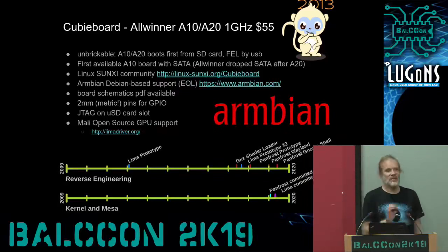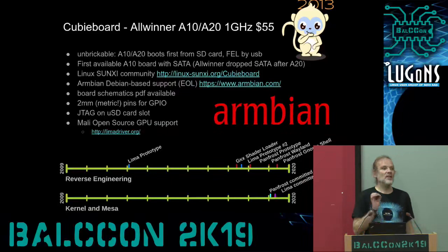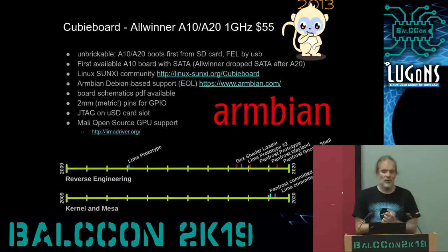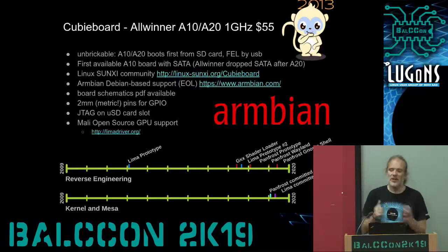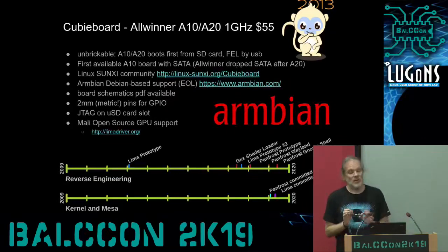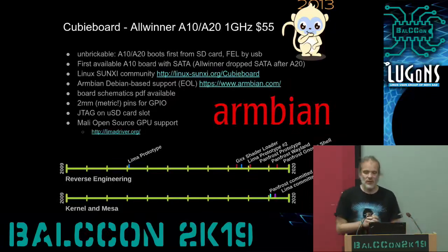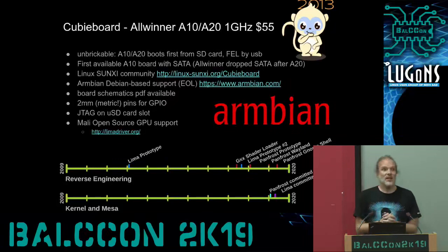The CPU itself is designed in such a way that it will boot from the SD card if the SD card is present and has the correct magic values and bootloader on it. So it's also unbrickable. You can do anything with it. It also has the ability to boot from USB. It's called FEL in Allwinner. And it had a really good community